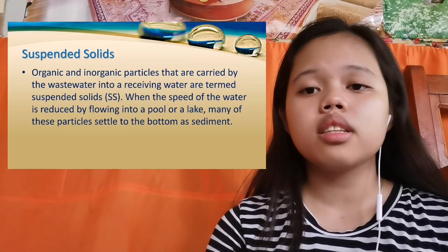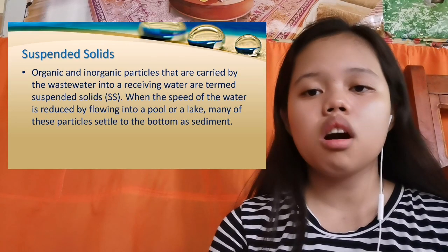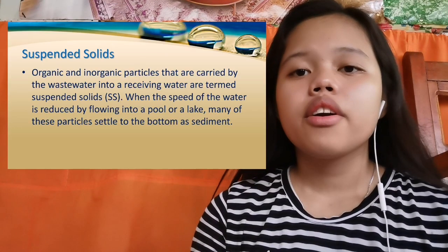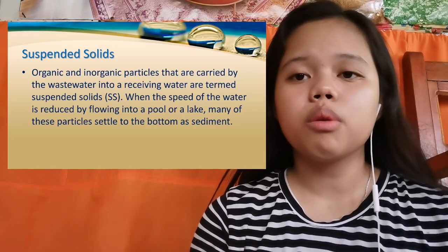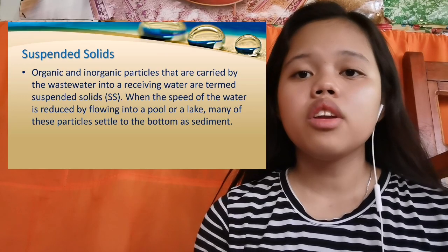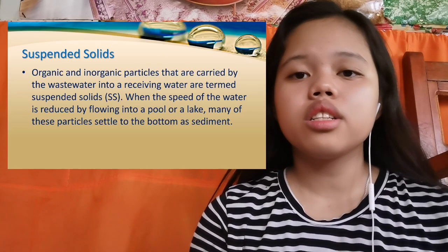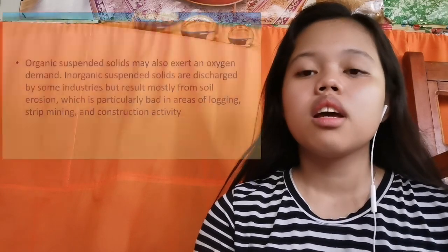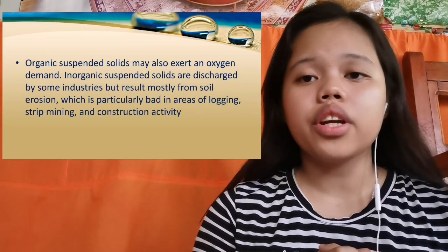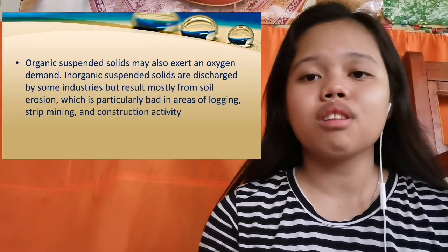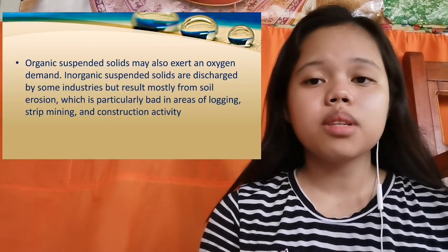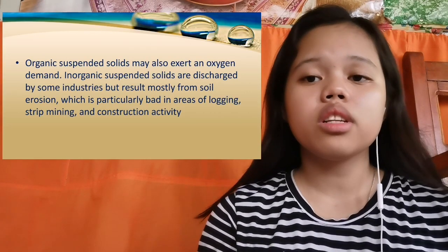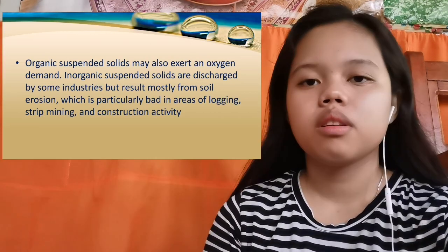Colloidal particles that do not settle readily cause the turbidity found in many surface waters. Organic suspended solids may also exert an oxygen demand. Inorganic suspended solids are discharged by some industries but result mostly from soil erosion, which is particularly bad in the areas of logging, strip mining, and construction activity. As excessive sediment loads are deposited into lakes and reservoirs, the usefulness of the water is reduced.